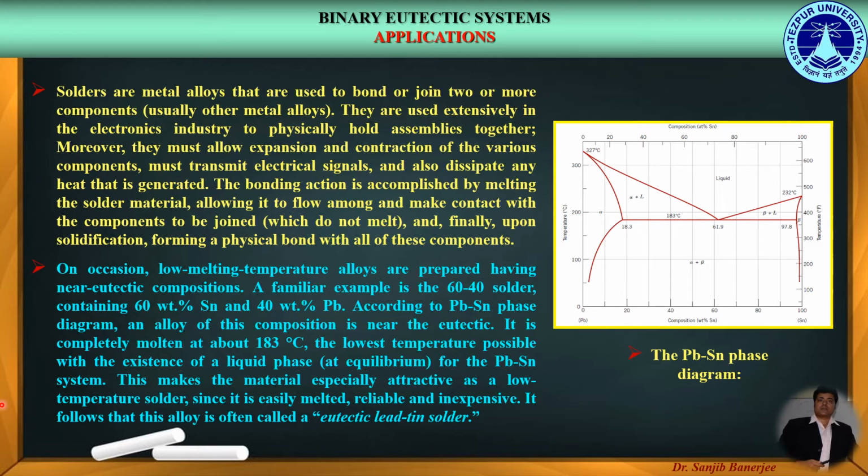They must transmit electrical signals, and they should dissipate any heat that is generated. Now the bonding action is accomplished by melting the solder material, allowing it to flow among and make contact with the components to be joined, which usually do not melt, and finally upon solidification forming a physical bond with all of these components.